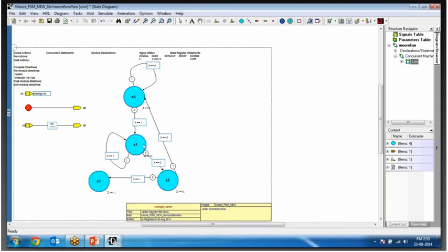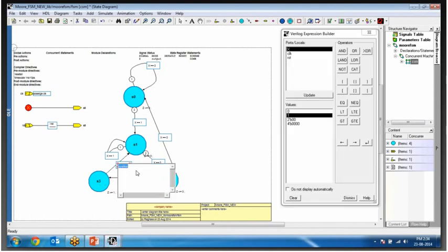So what happens after finding the 101 pattern, that is 1 0 and 1 here again? How do we find an overlapping pattern? We have to have a connection between S3 and S1 to find the pattern of 1 again. For that we need a last transition. I don't have much space, so I'll just move this arc around. This is more convenient now. So now I'll go directly to the connection between these two, state S3 and S1. I'll select this and give x is equal to 1.